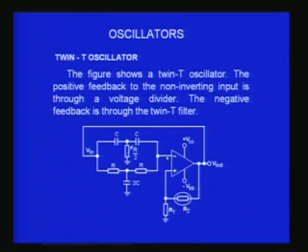circuit. So, we have formed a simple Wien's bridge network here, and you can see the circuit is very similar to what we have done in the case of Wien's bridge. We take the output and give through the twin T network and connect it to the input. So, this is used in the feedback network, so with 0 phase shift. So, once you do that, you get an oscillator output which is again in the form of sine wave, and you can see the values of the capacitor and C is given here.